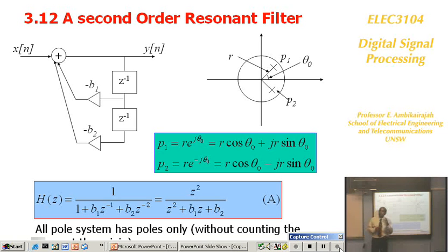Okay? If you take an all pass filter, you make sure that wherever the pole position is, keep it inside the unit circle and reflect the pole position to outside and convert that into a zero. And if you do that, then it's an all pass filter with a different phase. So where do you use all pass filter? You want a signal not attenuated, but phase to be changed. Use all pass filter.